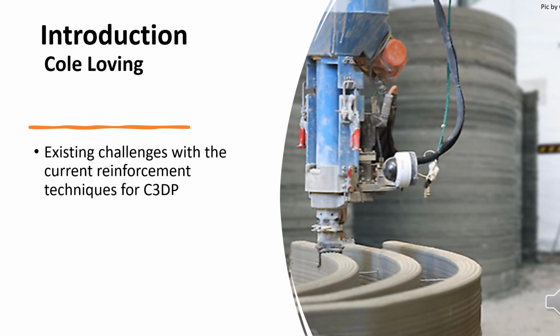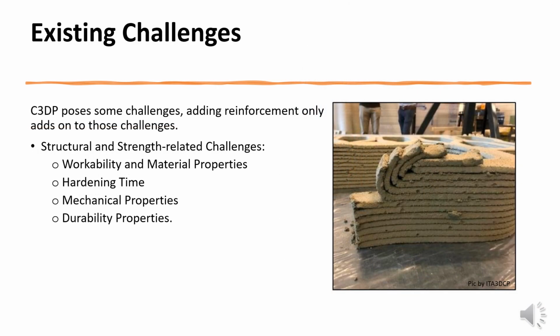Hello everyone, my name is Cole Loving, and today I'm going to be discussing some of the existing challenges with the current reinforcement techniques for C3DP. C3DP poses some challenges because there are multiple moving parts between the motors, pumps, and material, and everything must be perfectly synchronized. Trying to add reinforcement techniques into the mix is even more challenging.